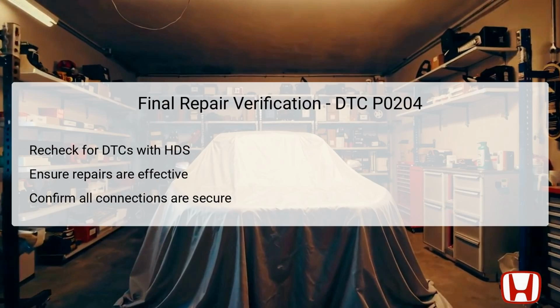After completing all necessary repairs related to the DTC P0204, it's vital to verify that no issues persist. This verification involves rechecking for any remaining diagnostic trouble codes using the Honda Diagnostic System HDS.